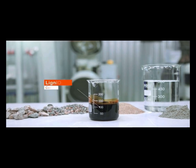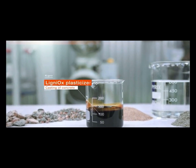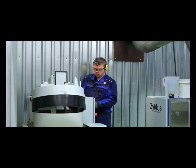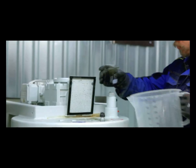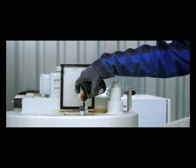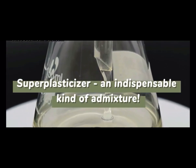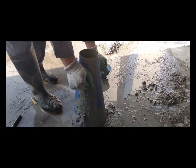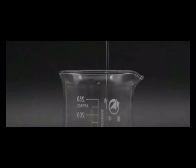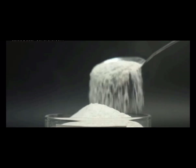Now is a great time to talk about the hidden stars of concrete manufacture, the admixtures. These chemicals offer a range of advantages and may be added to concrete to improve its properties. Plasticizers give the concrete greater workability, which refers to its ability to be easily molded and placed without segregation or excessive bleeding of water, allowing it to reach congested areas. Accelerators or retarders are another type of admixture that speed up or slow down the setting time for concrete.